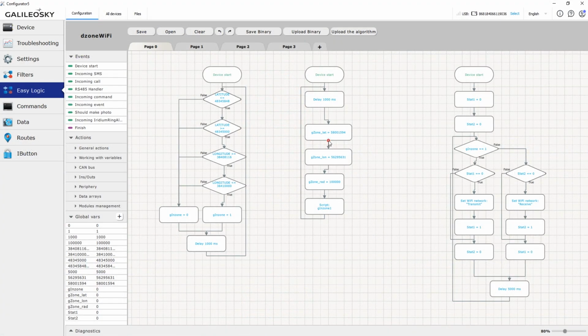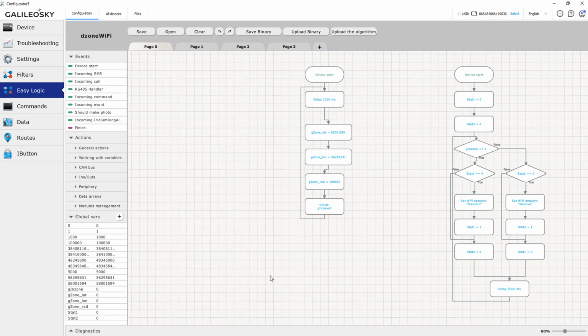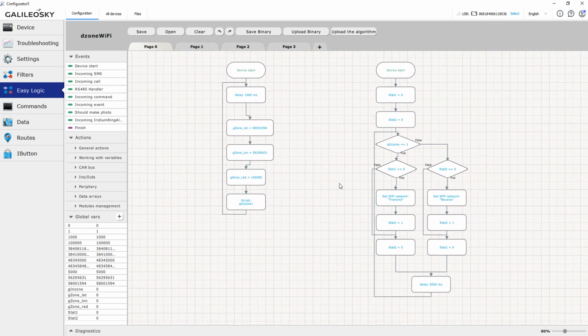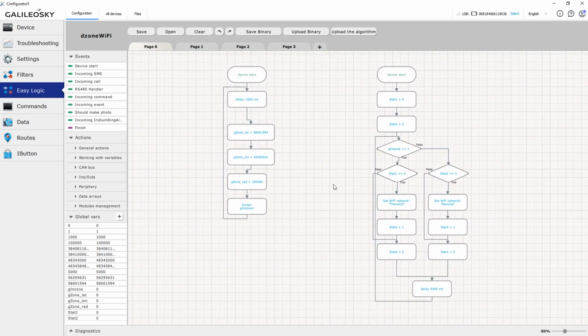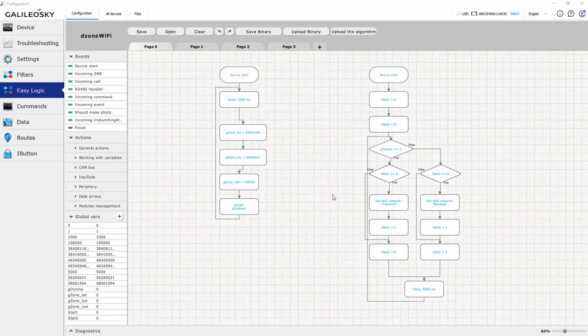Do not forget to delete the other chain when you choose the geofence type. For example, I set the center of my circular geofence and its radius. In this geofence, my tracker must switch to the client mode, so I remove the chain that describes a rectangular geofence. You can't leave both chains because in this case the algorithm won't work correctly.